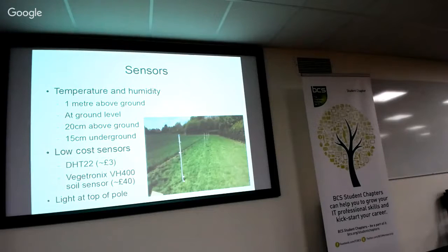And we have soil temperature sensors, which are these things that you can buy from Adafruit or various other places online. And we've had a lot of problems with stuff that you bury, because you buy things that are marked soil temperature and humidity sensor from someone like Adafruit. You bury them in the soil, they work fantastically for about 3 months. And then you dig them up and wonder why they're not working, and then you take them apart and you realise that all the stuff that you thought was waterproof isn't waterproof. It's all gone green and corroded and died and stuff like that.